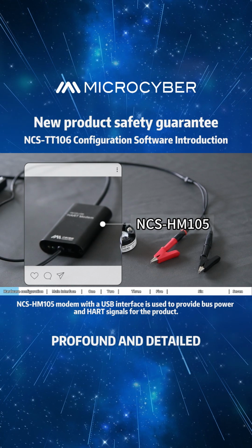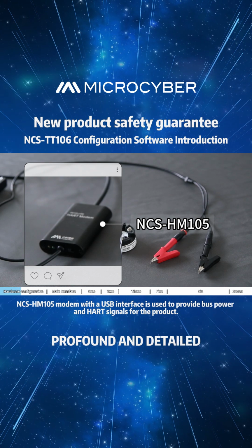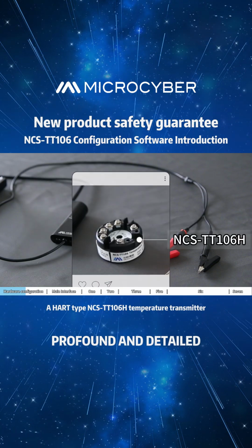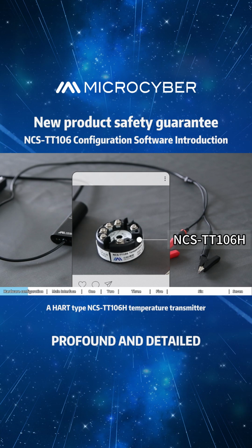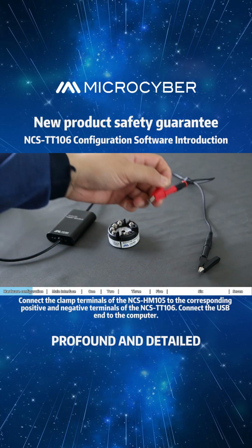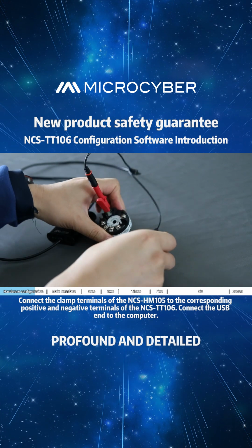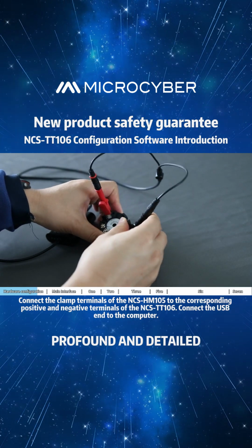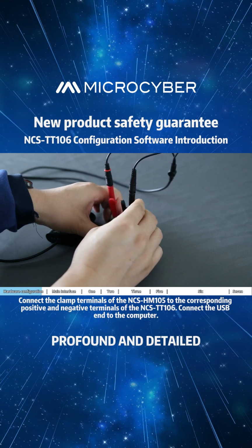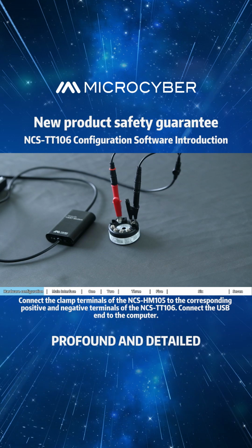The NC-SHM105 modem with a USB interface is used to provide bus power and HART signals for the product. A HART-type NC-STT106H temperature transmitter. Connect the clamp terminals of the NC-SHM105 to the corresponding positive and negative terminals of the NC-STT106. Connect the USB end to the computer.